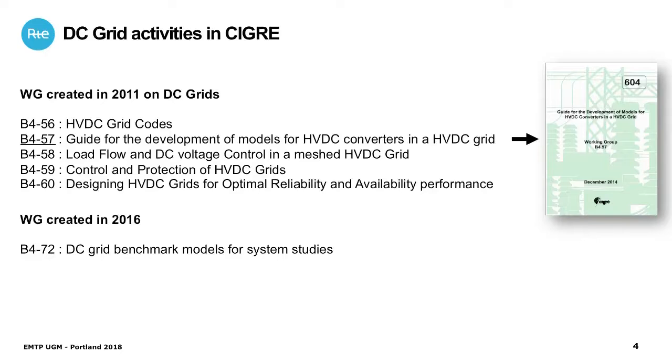We worked on the development and implementation of the first large DC grid for CIGRE, which was not called a benchmark at that time, more a test system. It was implemented in 2013 in different EMT tools, and all the details, all the data, equipment, but also control system and protection, have been documented in the final technical brochure you have here on the slide.